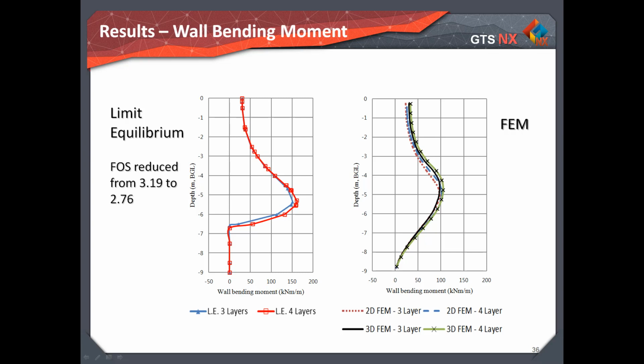The wall bending moments show less proportionality, especially for 2D and 3D FE models, which predict the maximum wall bending moments to be approximately 30% lower than limit equilibrium method suggestions. The 3D model correctly suggests the worst case scenario occurs at middle columns. Thus, the graphs for 3D method are based on this specific location.